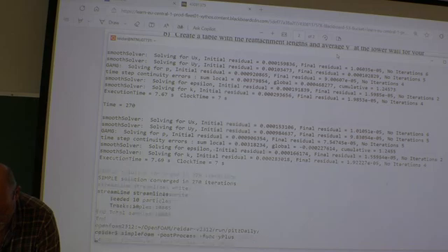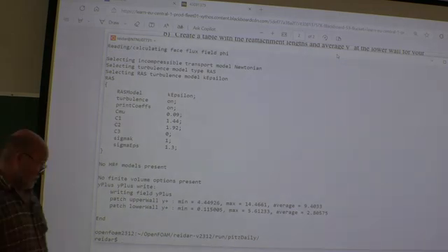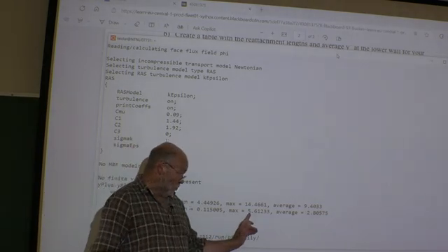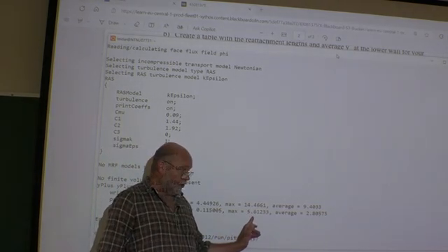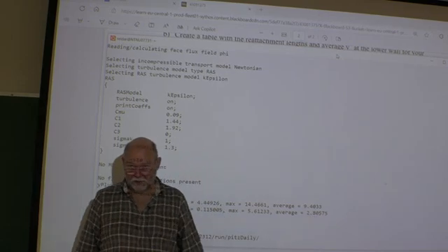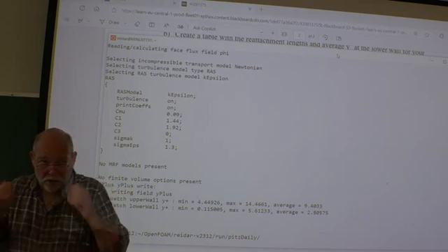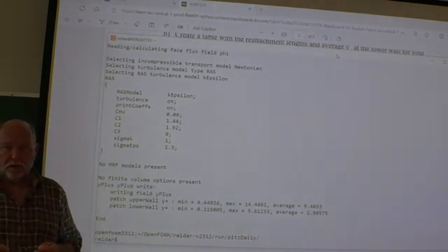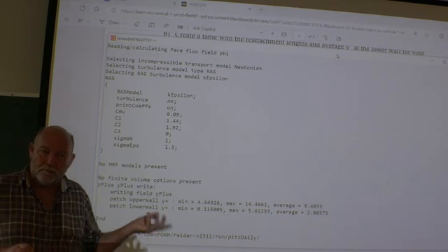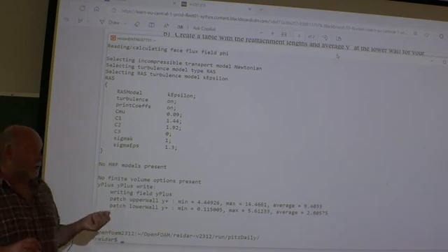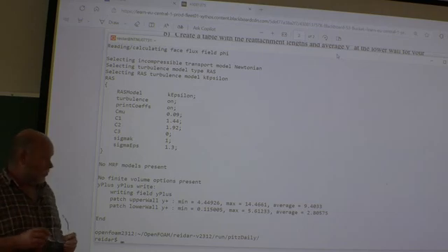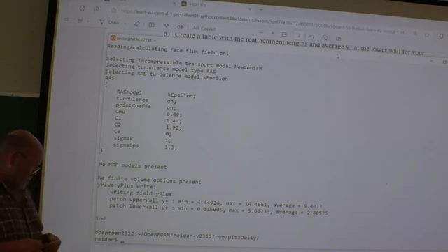Here we are, the y plus. Look at the lower wall. Now we're talking 5.6 and 2.8. Now I am below 6. So now I could use normal boundary conditions without wall functions for the different turbulent parameters. I haven't done it. We still have wall functions. So the solution here may be a little bit off, but never mind. Let's just have a look at the mesh, what it has done.